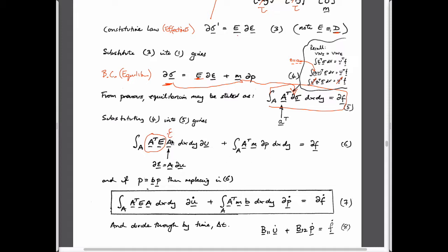It did have the strain in here, but we can swap the strain out for displacements, which are one of our primary variables. And all we need to do is also realize that fluid pressures are equal to the shape functions multiplied by the nodal magnitudes of those fluid pressures. If we look at changes in those, then we can just pre-multiply them by changes. And so if we switch that out, and that's basically what this expression is, then we end up with a relationship which is this.